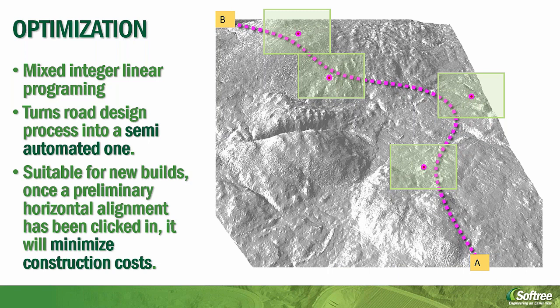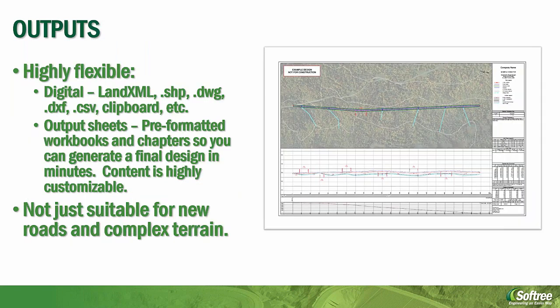Now in version 9, there's also a horizontal optimizer, so that'll look at the whole process from a 3D perspective. It'll move your plan view or horizontal alignment over, and also figure out the best vertical alignment all simultaneously. So pretty powerful, pretty cool. I do think that's kind of the future of road design. I think that's going to especially play a part once things like RTK-equipped GPS equipment become more common, and you can have your dozer operator, for example, driving along and their blade automatically adjusting to match that design surface.